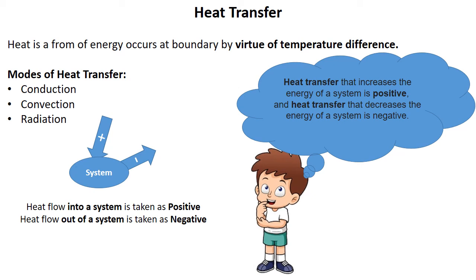For example, if you have a cup of tea, the heat transfer takes place from the cup of tea to the surroundings until the system and the surroundings are in equilibrium, that is, it reaches the same temperature as the surroundings. The heat transfer solely occurs because of the temperature difference between the two systems. Hence, heat is a transient phenomenon. The temperature difference is a cause or a potential, and the flow of heat is called flux.